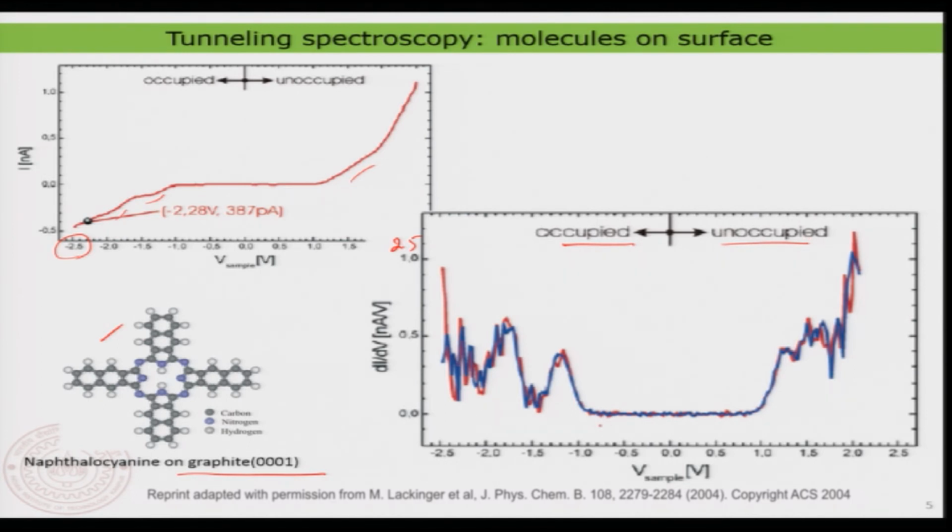And now you clearly see that there is a region inside, which is some kind of region having no density of states. Then suddenly, around minus 1.25 volt, I have a resonance, and again when I go somewhere around 1.7 or 1.8 volt I have a resonance, and then the density is basically increasing. On the positive side it is more interesting because you do not really see discrete levels there, but you can see the density is somewhat changing like this. That means you might be having electronic states that are very close to each other.